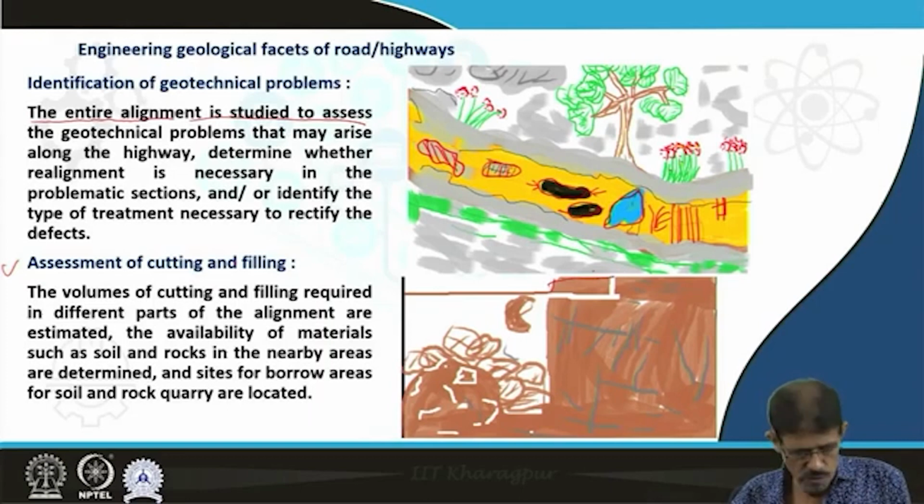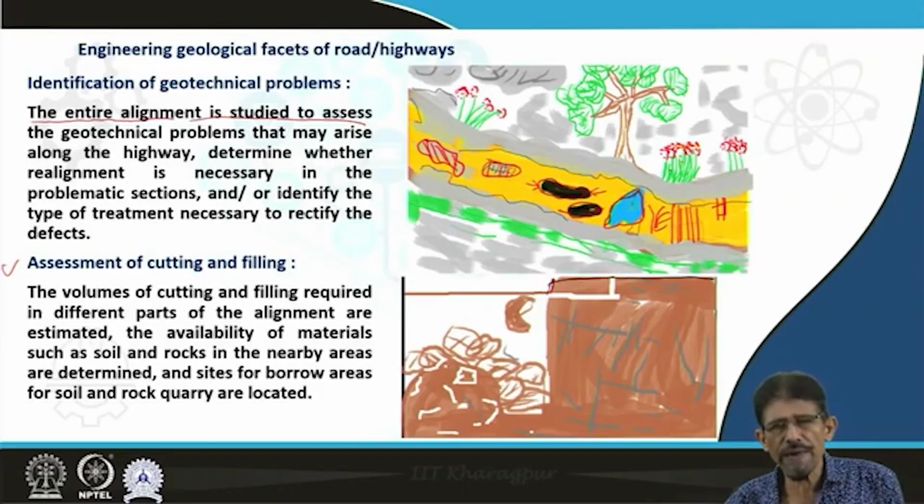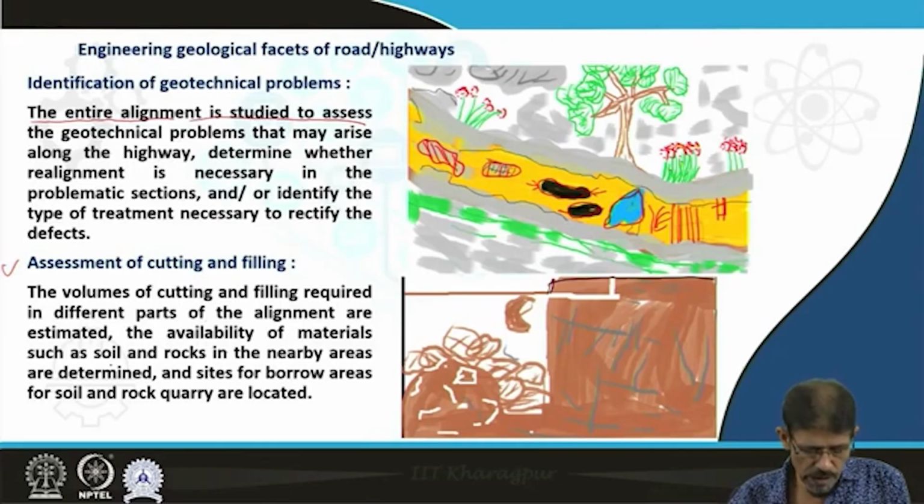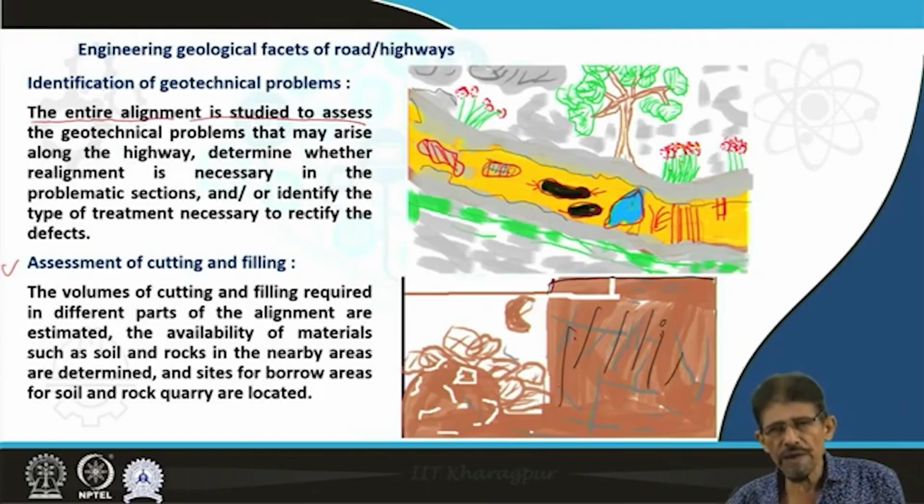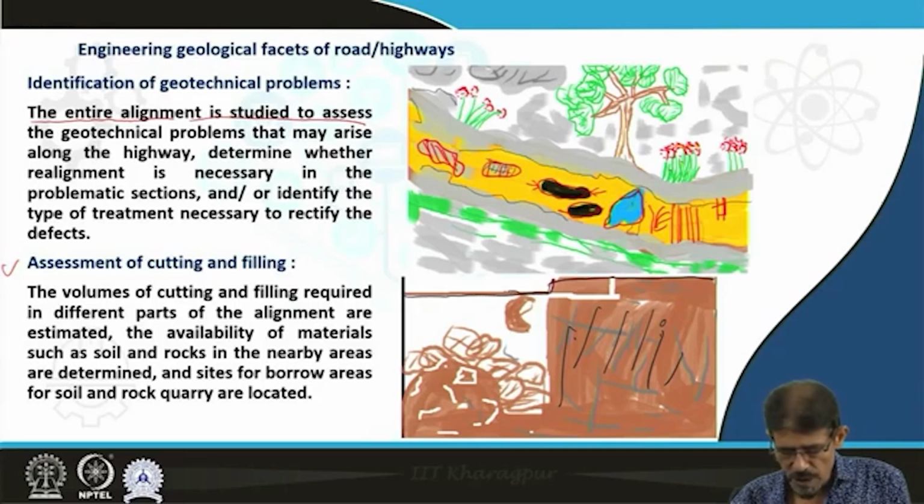Friends, as we know that the subgrade is not of defined planar nature, as per requirement we are going to see the subgrade. It is made up of soil or it is made up of rock, it is weathered in nature or intact, it is weak or strong. Then as per level of road, suppose the level of road is defined up to this, then we are going to make some provision for cutting this zone to make the level, and where the other side is depressed in nature, we are going to fill this material in this zone.